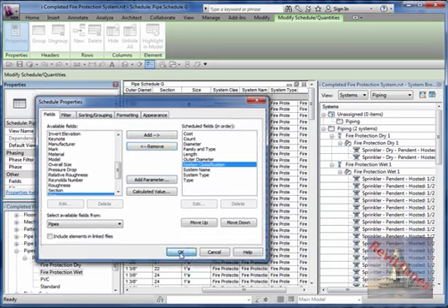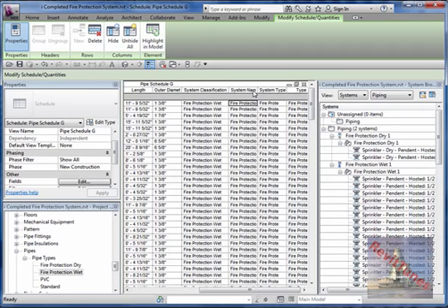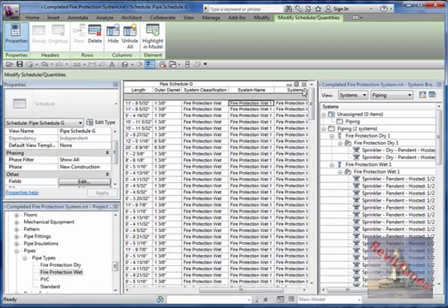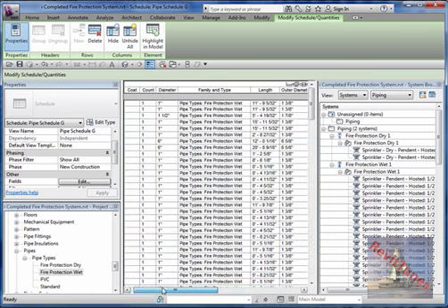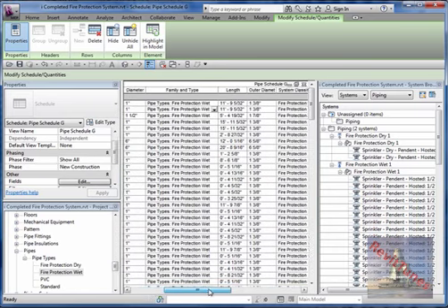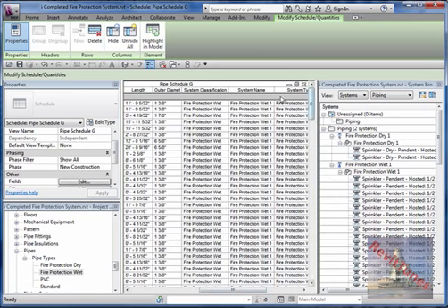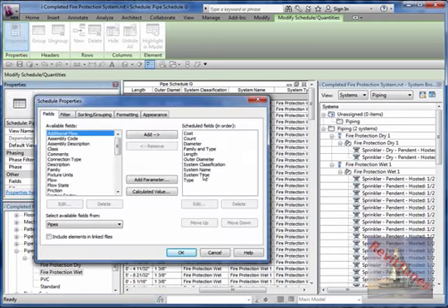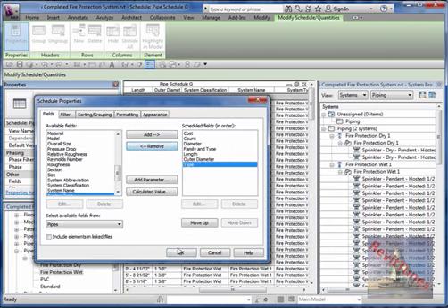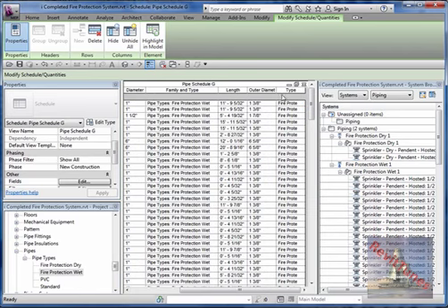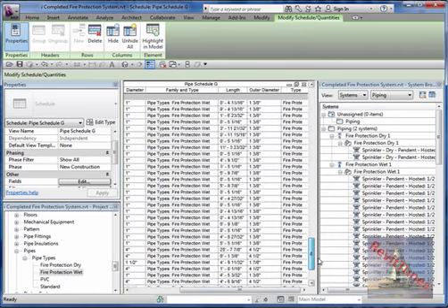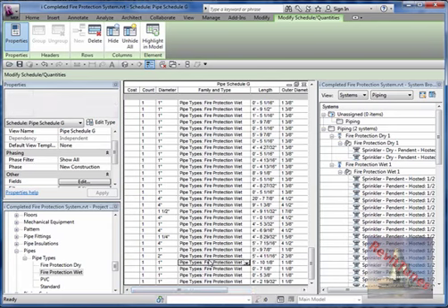And now I'm going to double click here, because we have the type right here. I don't really want to get information about the system, so I will remove system. I just want pipe type, no system type right now. So no system information at this point. And the type of pipe is fire protection, we already know, and over here it's already included, so I will remove the last one.